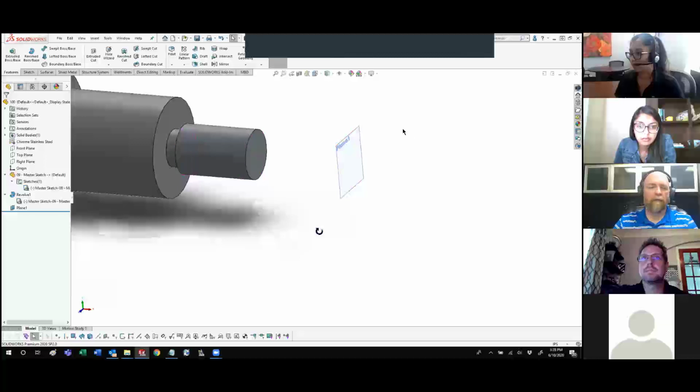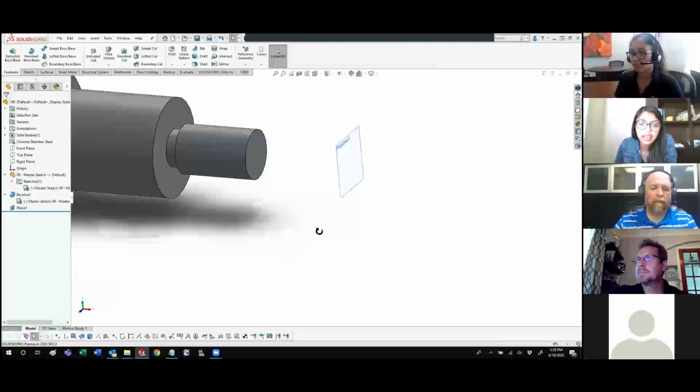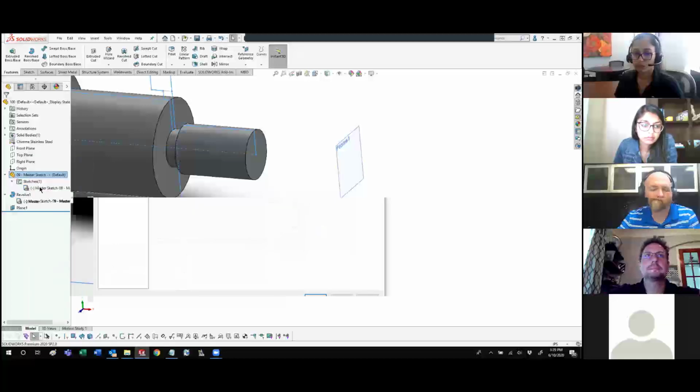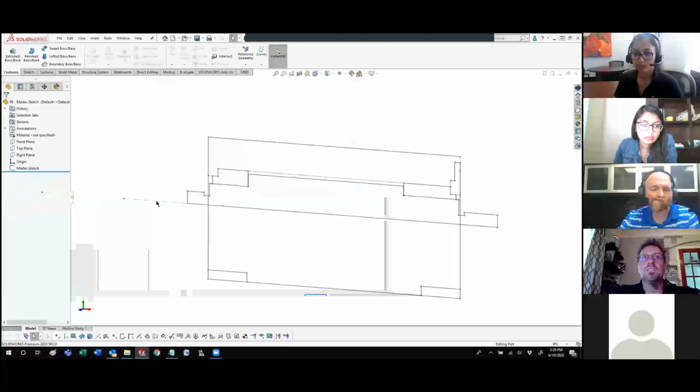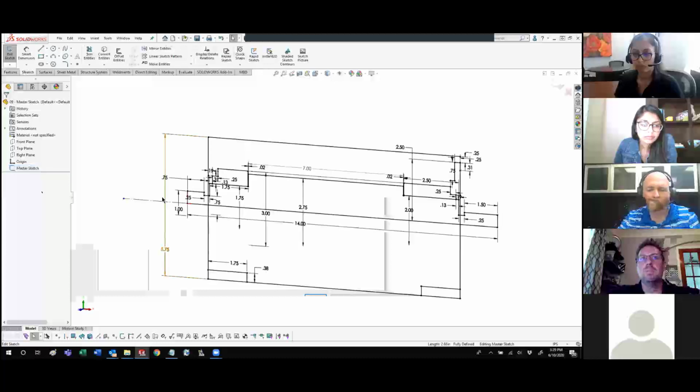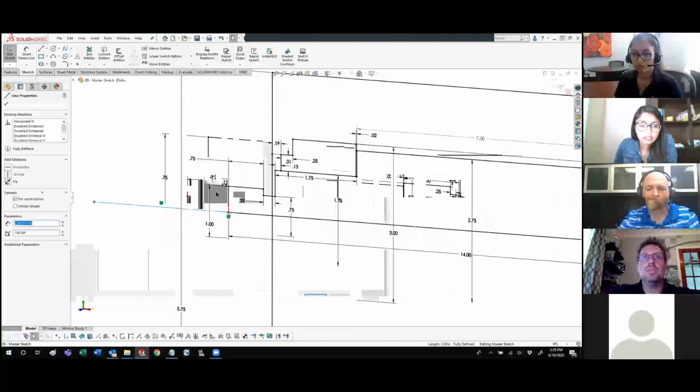Okay, what else? Could it just be that the axis you revolved around in the master sketch is the one that's not fully defined? It might be. I don't know. I typically don't put a dimension on stuff like that, but I do typically put a relationship. I'll just make this equal to something.